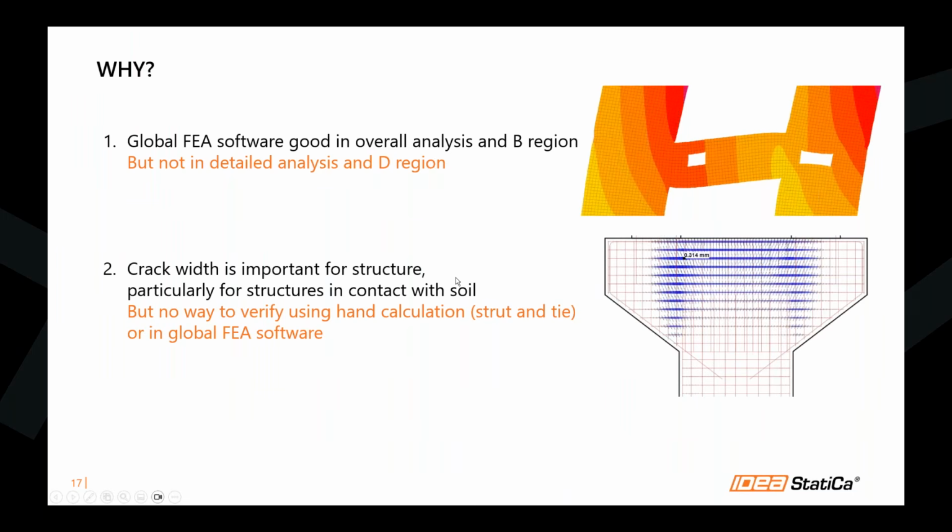Next, crack width is important for structures. It's a serviceability limit state, particularly when we are talking about underground structures. For structures that are in contact with soil, there are more stringent requirements to check and make sure that the crack doesn't pass certain limits. This is done to prevent corrosion of the rebar.